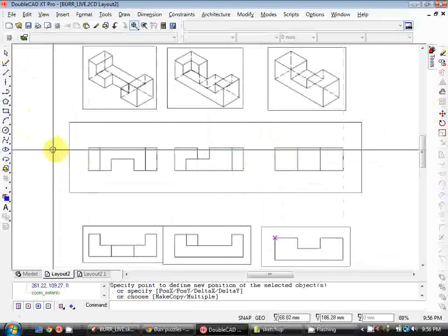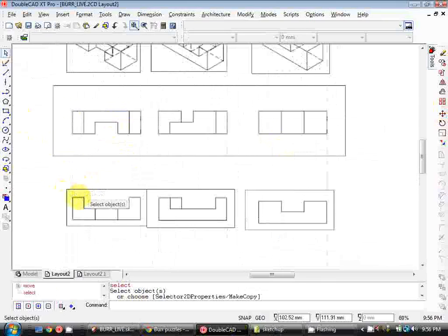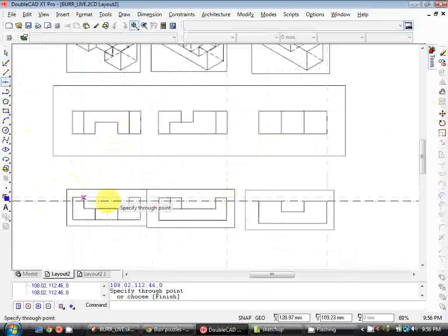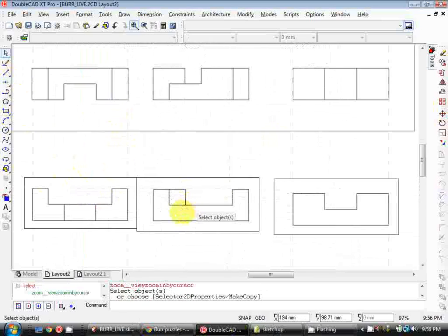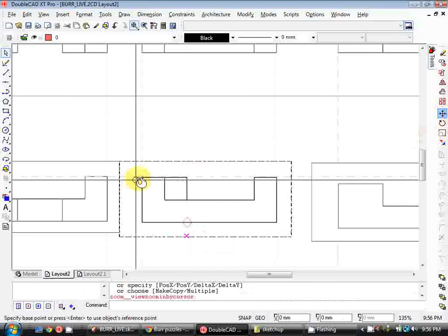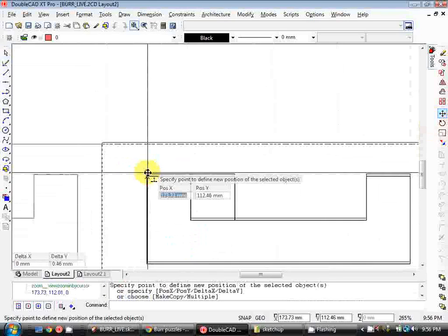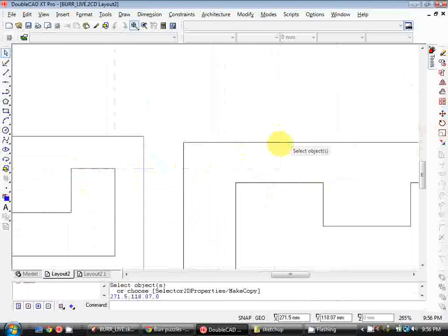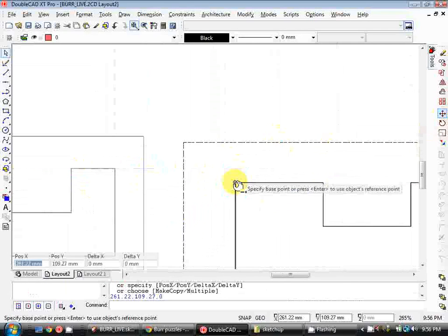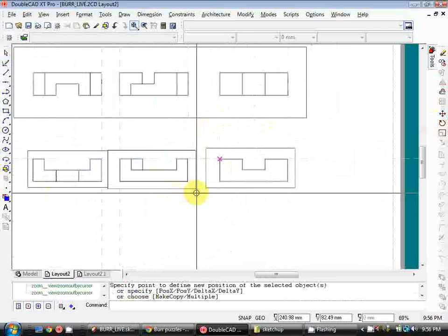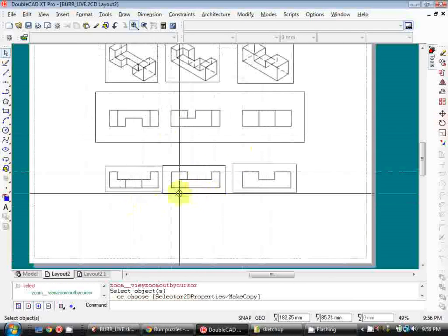And I'm also going to draw now a construction line horizontally across these, so I can line the tops of these blocks up. So if I click and hold, I'll get the horizontal construction line, snap to the top of my block 1. Then if I zoom in a bit, I can select the viewport, and using that top corner, snap it up to this construction line. And I'll repeat this again, snap up to there. So I'm going to repeat that process again for the back views. I'll skip ahead and then we'll get on to labeling these views.